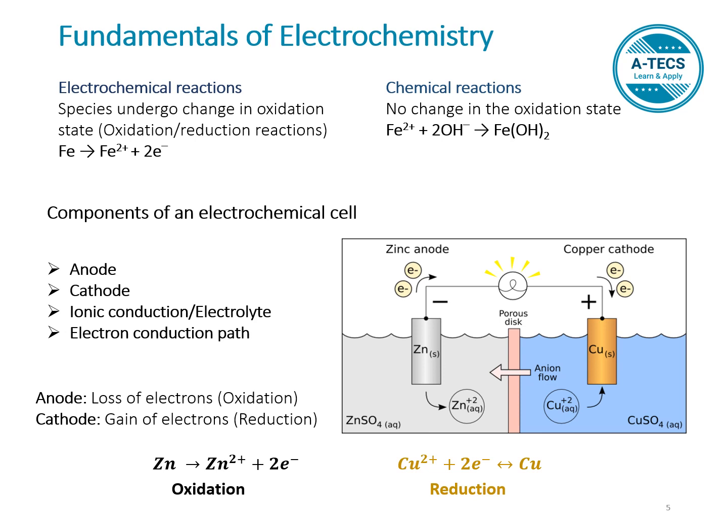To support anodic and cathodic reaction in an electrochemical cell, we also need 2 conductive paths. One is ionic path, the second is electronic path. Because in an electrochemical reaction, as I discussed earlier in an example, iron is oxidizing to iron 2 plus and generating 2 electrons.